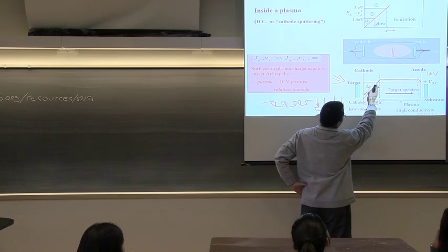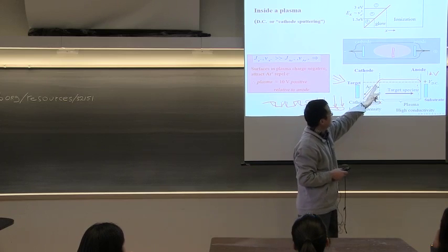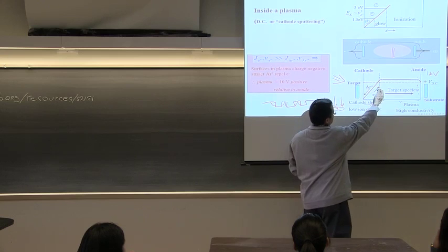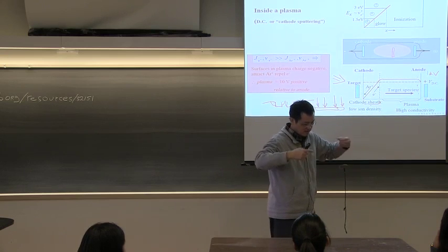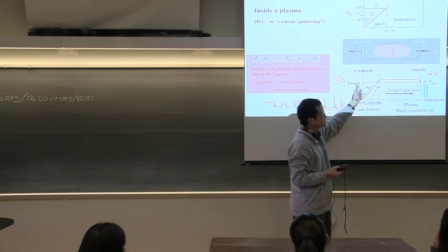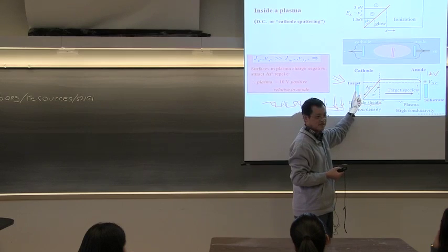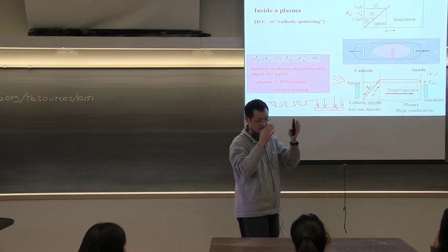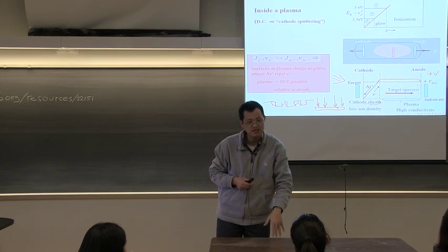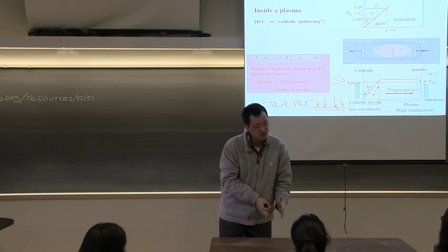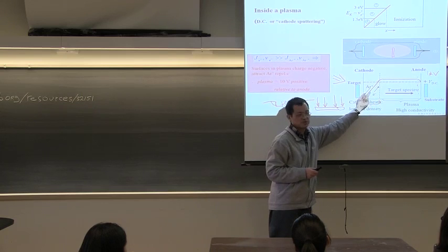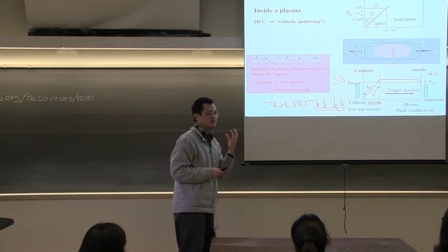Now, let's first hold off on explaining why it exists, and just look at what this effect will do. If an argon ion, which is positively charged, comes into this region, it gets accelerated. When the argon comes to the target, it doesn't land at all sorts of different angles. It all comes in normal to the substrate. In the meantime, it has energy, and this is very helpful because when we discuss etching later on, we want the etching gas to come in normal to the substrate, and this way we have what we call anisotropic etching. So we love the plasma because it has positive ions coming in normal to your substrate, with enough energy to etch the substrate or the films.